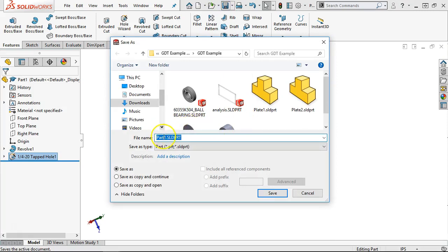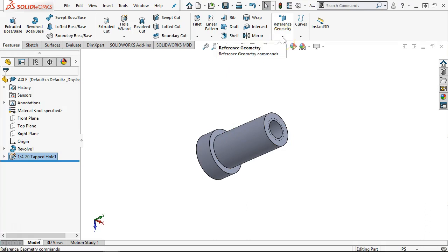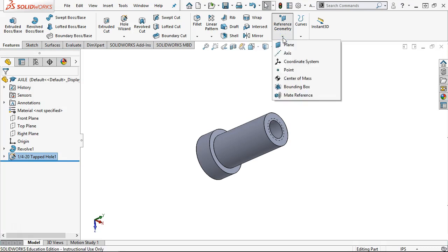And since I'm applying names rather than generating part numbers. Oh, well, it's axle now. Then the other thing that I would want to consider is I think we did this with the spacers, but I want to revisit it because it's such a handy tool on the SolidWorks design side, as our assemblies become more complicated and we're having to deal with more of these parts and components. Under the reference geometry, you'll have a mate reference.